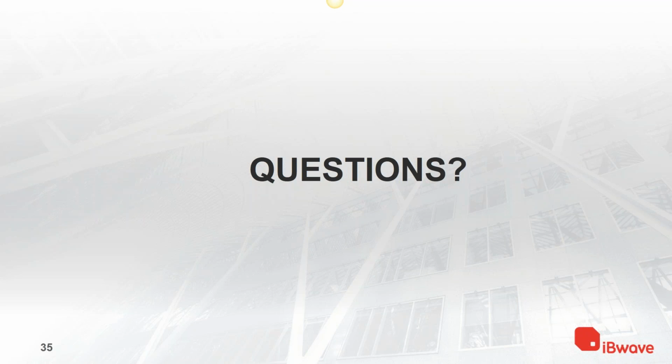Thank you. Let's see another question. What is the best model to use for a venue with a lot of reflections due to metal surfaces? Well, first of all, if you have a lot of reflections, a lot of multipath, in a venue, I don't know if this is coming from the Wi-Fi world or LTE world, but the reflections and the multipath used to be a big problem before MIMO came in. MIMO really thrives in this environment if you have lots of reflections. So I would definitely use a MIMO system. I would not use a SISO system for a venue like that.